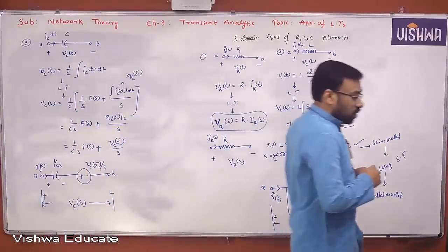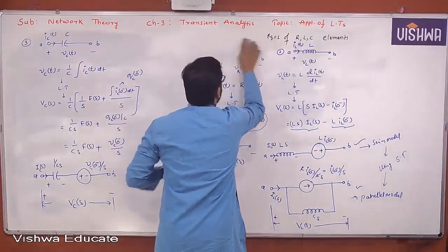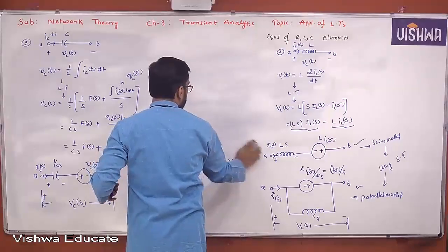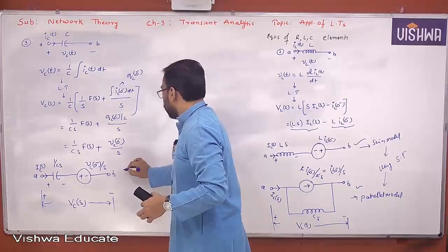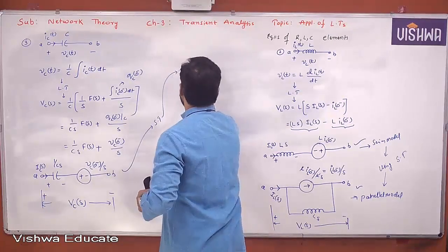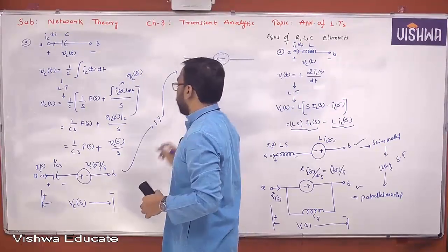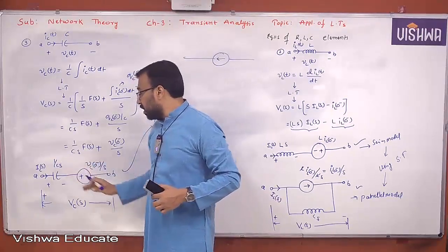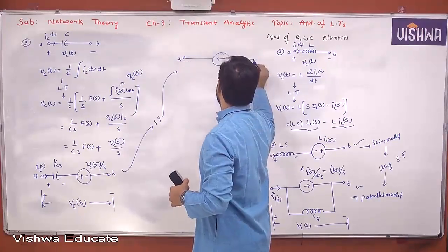Again, voltage source with a series impedance can be transformed into what? A current source with a parallel impedance according to source transformation. So let me draw now an equivalent here using source transformation. Now the current source direction is according to the polarities of the voltage source. You have positive here, therefore the direction of current is towards A. Okay, this is A, this is B,